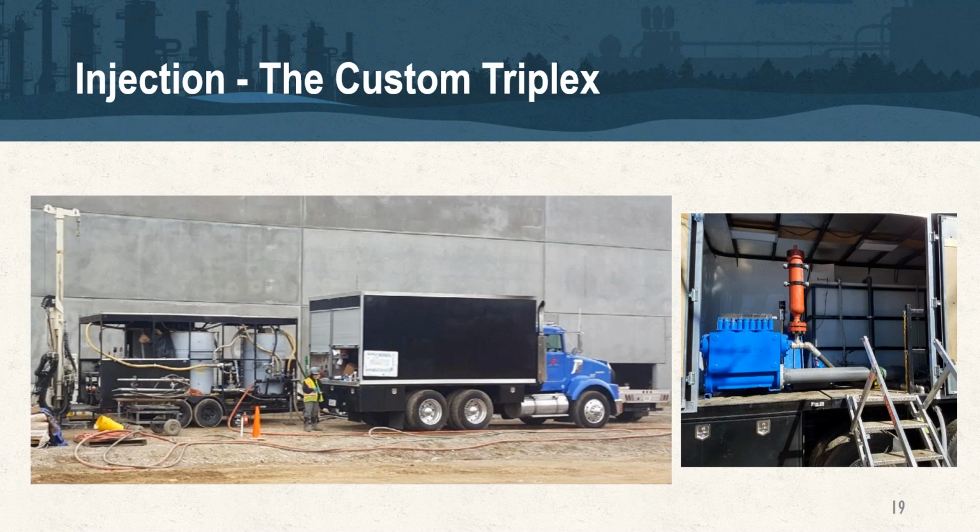The reason the trailer is there is that's our batch trailer. That allows us to continuously circulate and suspend product. And then when it's ready for downhole injection, we can transfer it over to the triplex to force it downhole through the injection packers.